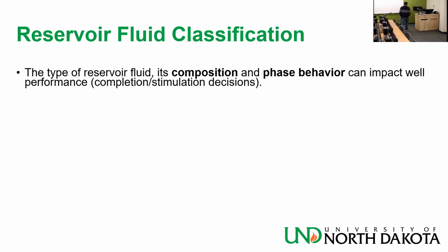I have seen carbonic acid not only destroying tubulars in a well, I have seen it destroying pumps in the lab. Generally, the rule is, if you're in a big lab with many labs, if we have a pump that is used for gas, it's only going to be used for gas. If it's a pump that is used for pumping water, it will only be used for pumping water. We don't mix the two.